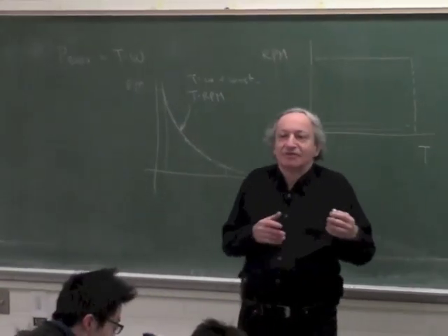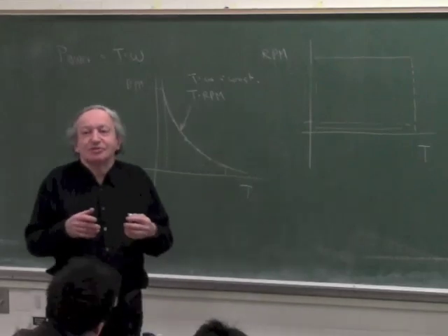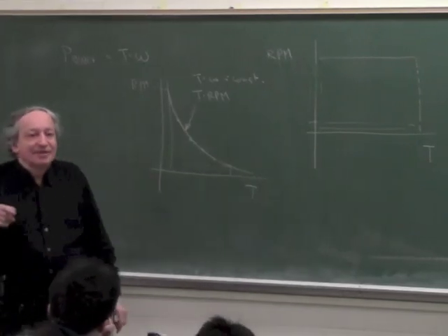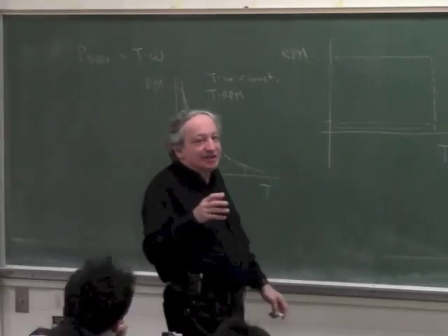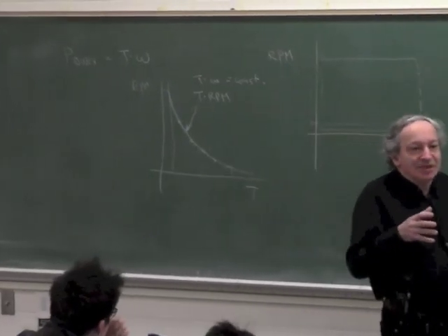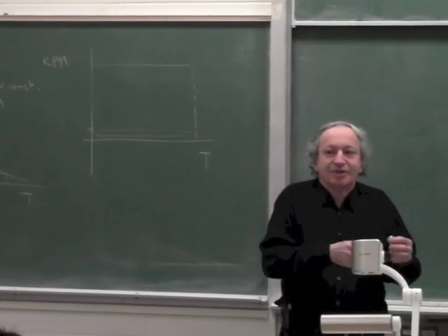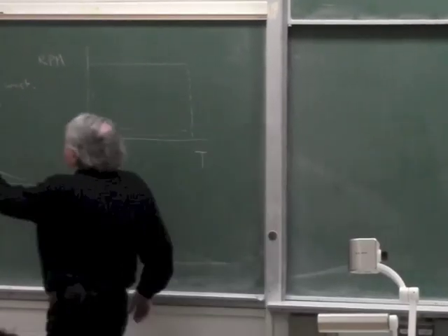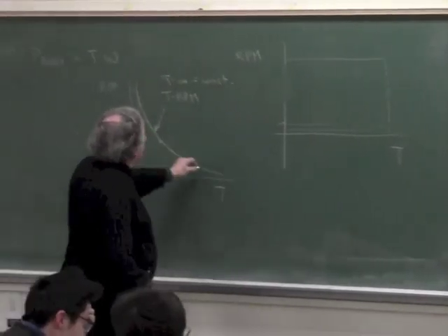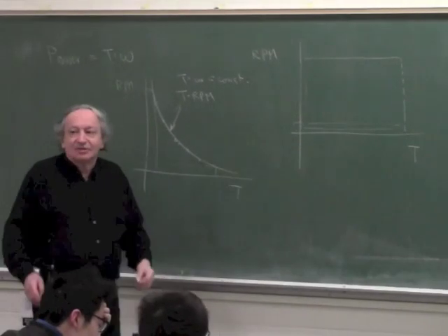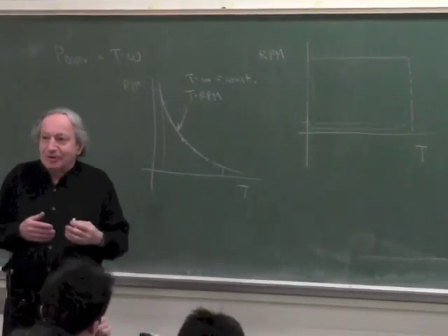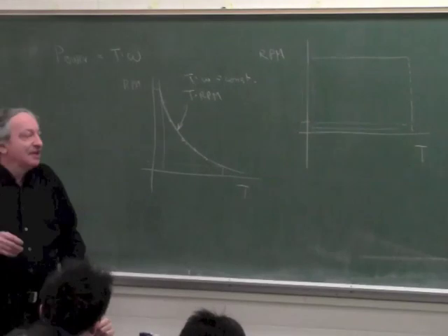A gear conserves the power; it just matches, so to speak, the impedance. In electrical engineering terms, a gear is an impedance match. Something wants to work at a certain speed and a certain torque, like here, but you have a motor which works here, so you have to use a gear. You keep the power constant, but you match the load.